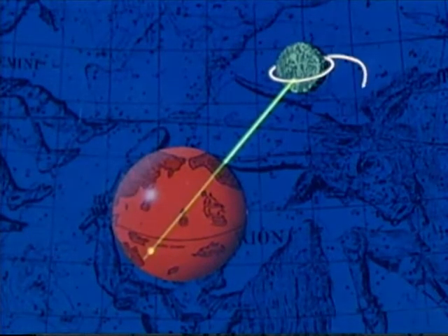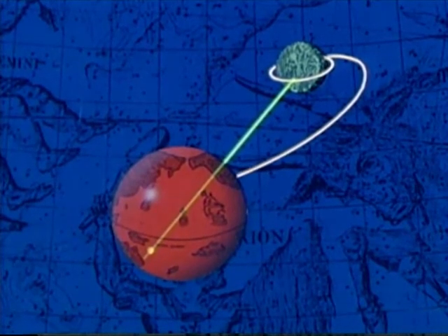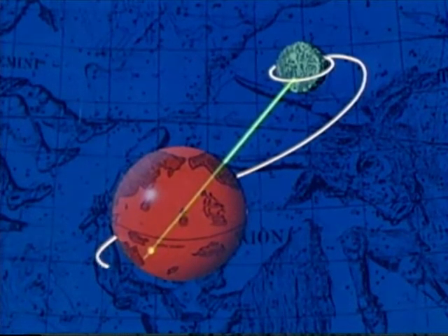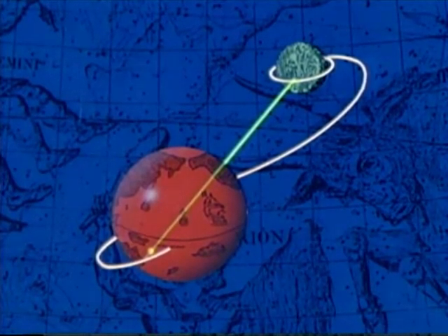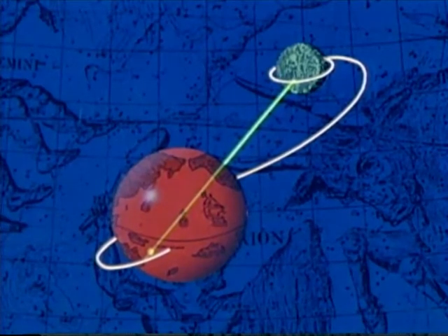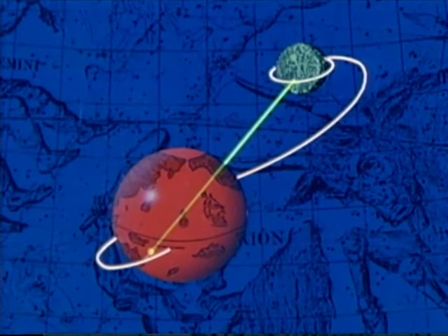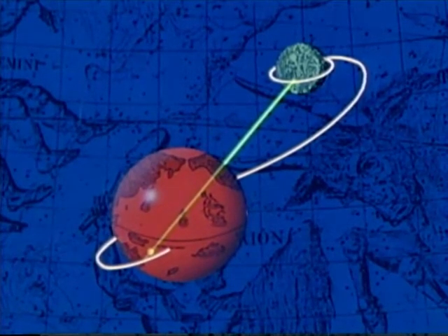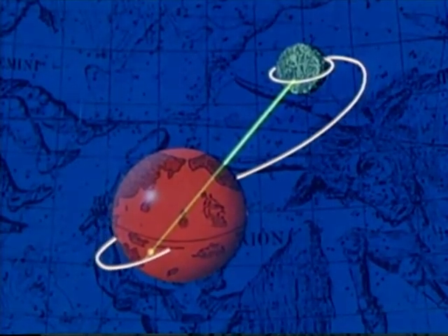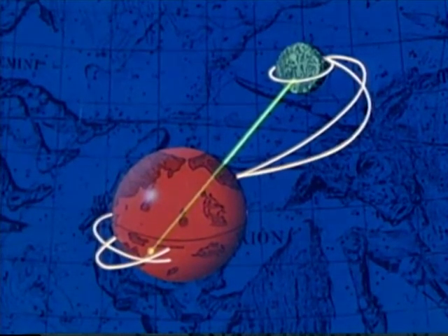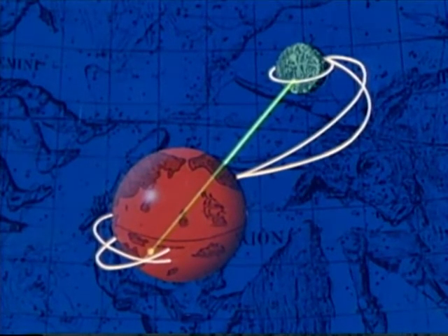The return trajectory begins at the Moon and must pass over the antipode. This means that the plane of the return trajectory must contain the Earth-Moon line. The injection burn to start the lunar spacecraft on its return trip will also fix the plane of the return trajectory. This plane can be rotated around the Earth-Moon line. The limits of this rotation are determined operationally. This range of planes, along with the entry range limits, determines the range of latitudes that can be achieved.